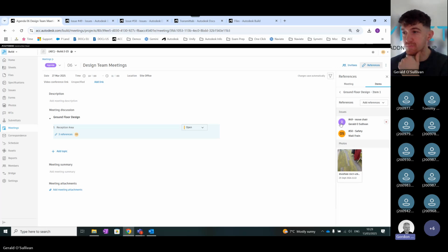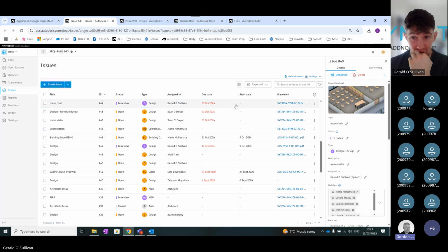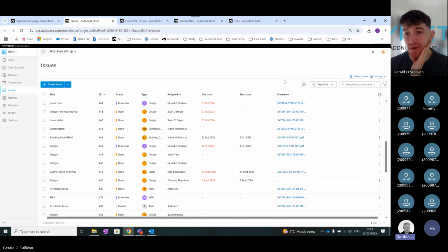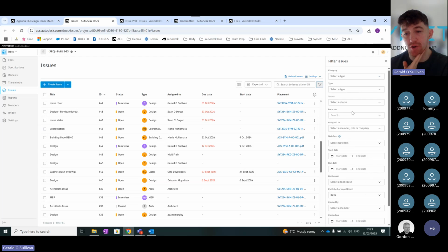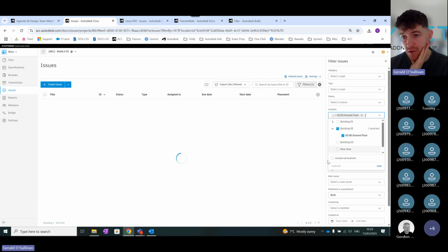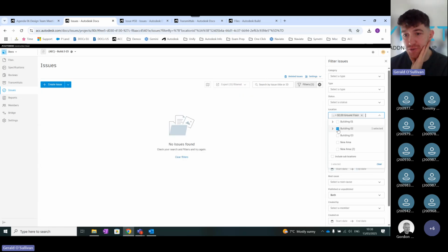Is that okay? Yeah. And just wondering when I seen your issues list, and I know we can filter the issues by whether it's coordination or design or whatever. But can we take a selection of issues and group them like we would do with clashes in Navisworks? There could be a random selection of issues, but they might all be within the plant room. So could I group them under plant room? Yes. Well, that'd be under locations, wouldn't it? Exactly. So inside here, you'll just have to make sure your locations are set up correctly, because if you select on these, then you'll have building, you'll have ground floor. You can select on that and it will bring up any issues that are then brought into that.